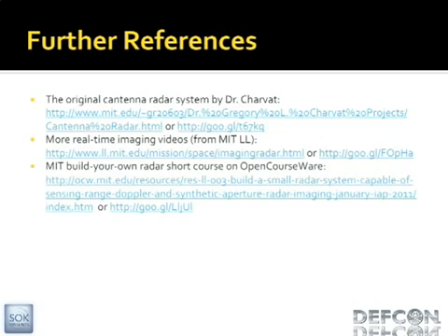Oh, yeah, actually that's worth talking about. He asked what the power requirements were. I believe this entire system uses about 200 milliamps at 5 volts. So like I said, it's easily powered by the USB port. It's the only power source here. The original was powered off of 2 sets of AA batteries. So that's about all you're talking about.